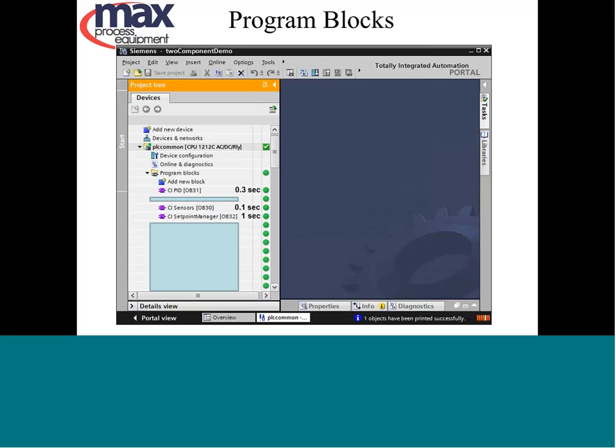The reason for this is that the sensor time rate depends on 3 things: the response time of the sensor and its associated data acquisition rate, the response time of the process, and the desired level of smoothing or filtering.